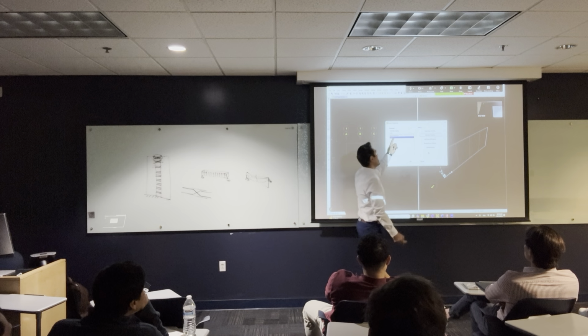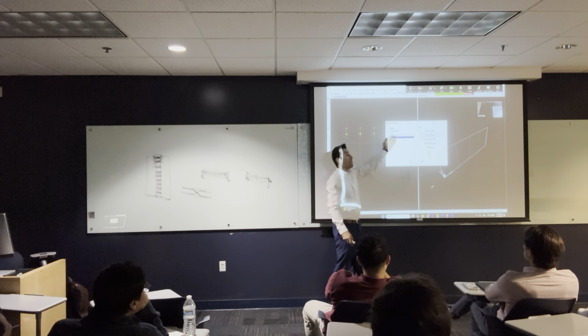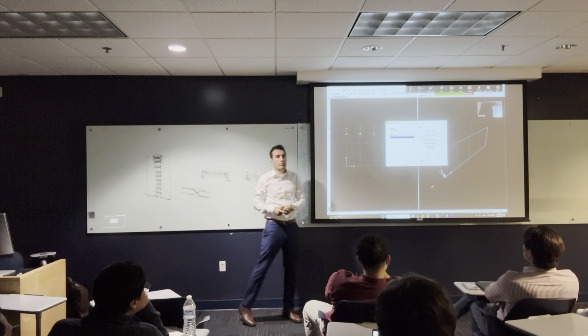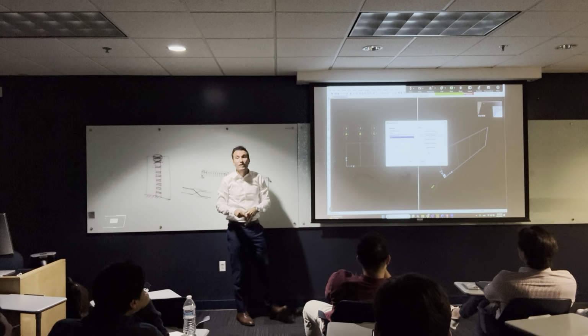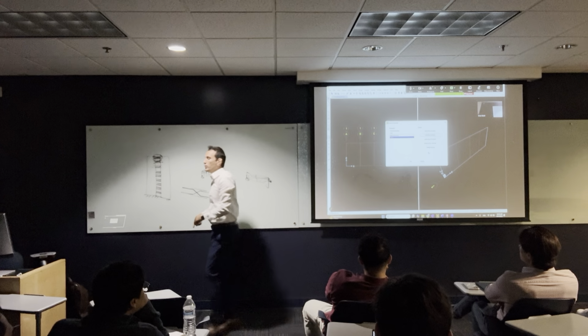So look at that. I defined here that the beam is 25 by 70 centimeter, but the unit wasn't meters. So the name doesn't matter. It's just a name. All what matters is the units inside the cross section. Okay? So this is how we can define cross sections. So let's say we are done with the cross section part.